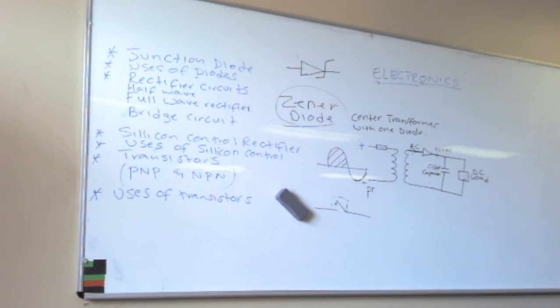That amount of AC current that penetrates through the diode is not required at all to go to the load. You hear me? When current crosses the diode, we need it to be pure DC current because it's going to a DC machine. If on the DC machine there is some current which is AC, that machine won't function properly.